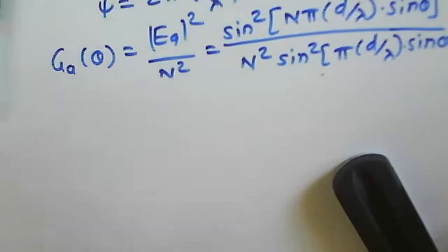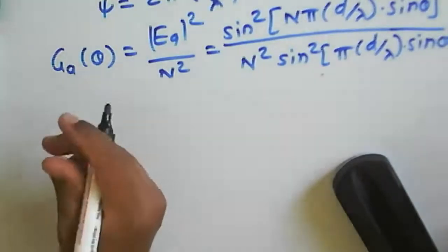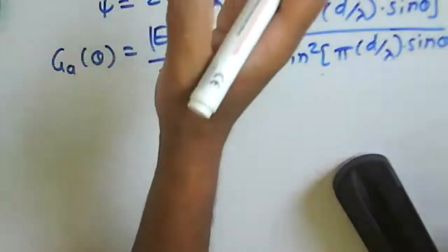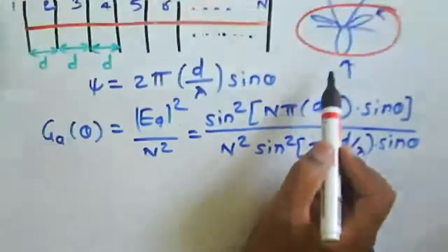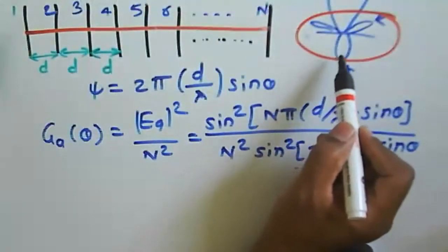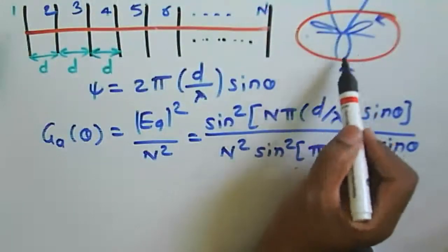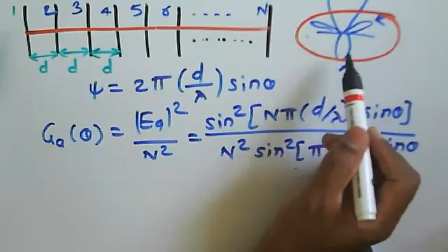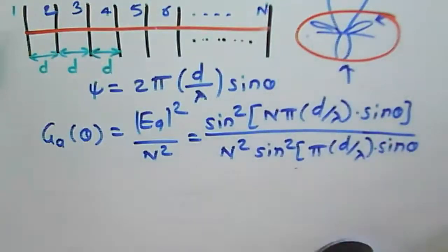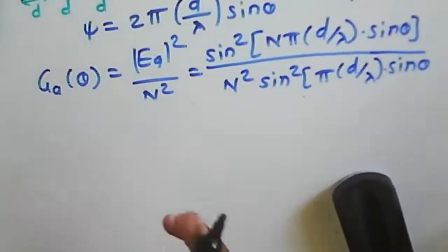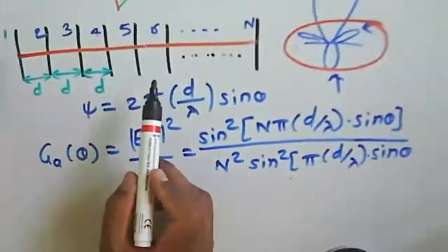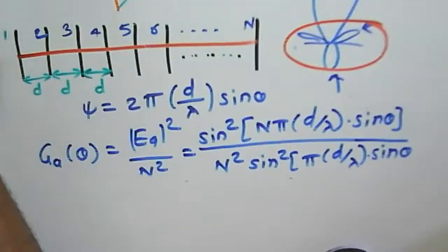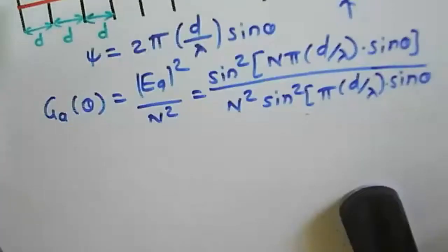We consider radiation elements in a given particular direction, a broadside array here, and we require no back lobe there. So what particular condition is to be used here so that we will not get any back lobe or side lobe there? For that purpose, we need to know about the elements present in this array antenna. All elements are directive, only in one direction, so directive elements are supposed to be considered.